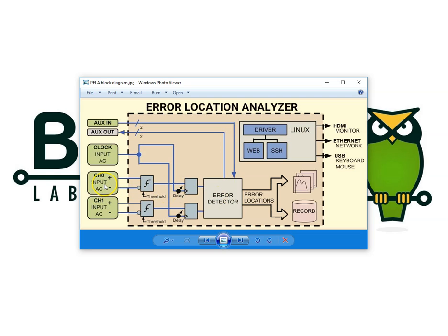These two streams can be thought of as one stream, as if they were bit interleaved, or as two separate streams. We could have different types of data present on different lanes, as long as they're all clocking at the same rate. The error detector's results are sent to a computer for processing, and the error locations, a log stream of information, can both be recorded to an internal solid-state drive and/or displayed in real time up on the graphs of the analyzer, allowing you to see the details of your error statistics.